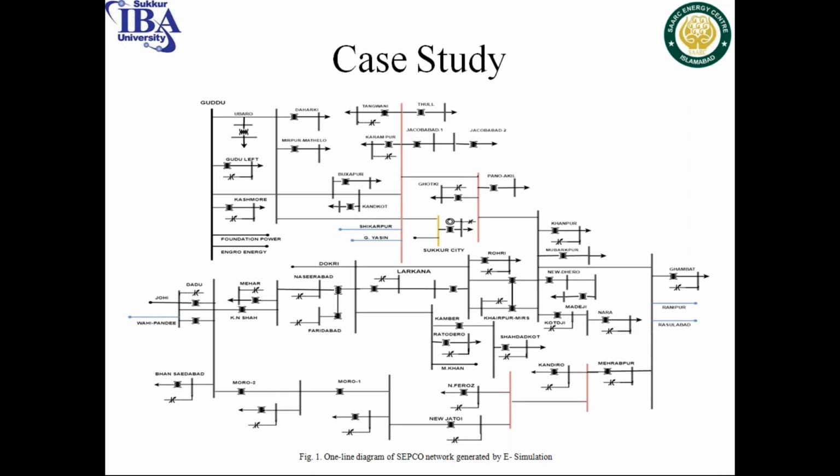Moreover, we can also use the phase shifting transformers. These are special transformers which are used to shift the phase of voltage from one angle to another. With this phase shifting, you can also compensate these losses. Also, auto transformers are used, but make sure that whatever the type of techniques, the modern techniques you are using, it should supply the reactive power, because we have to compensate those losses.